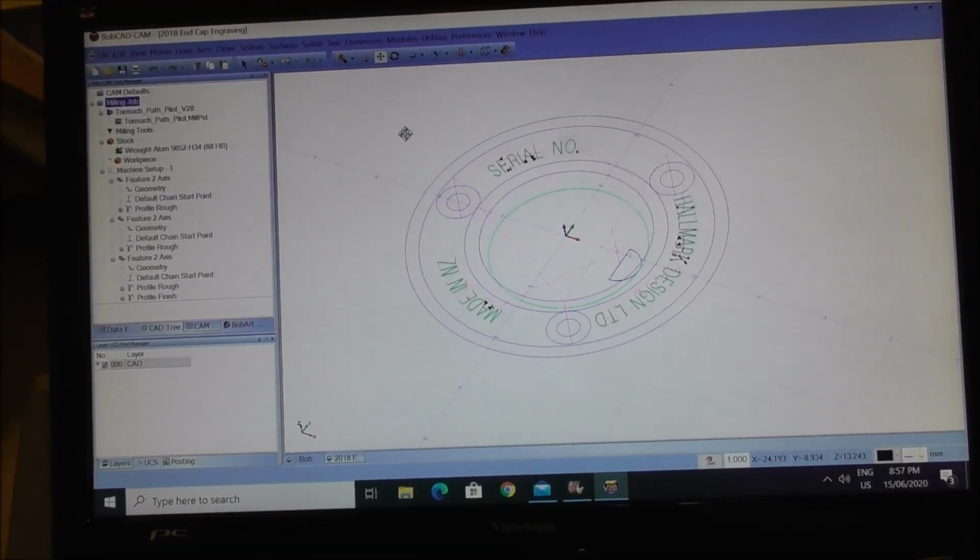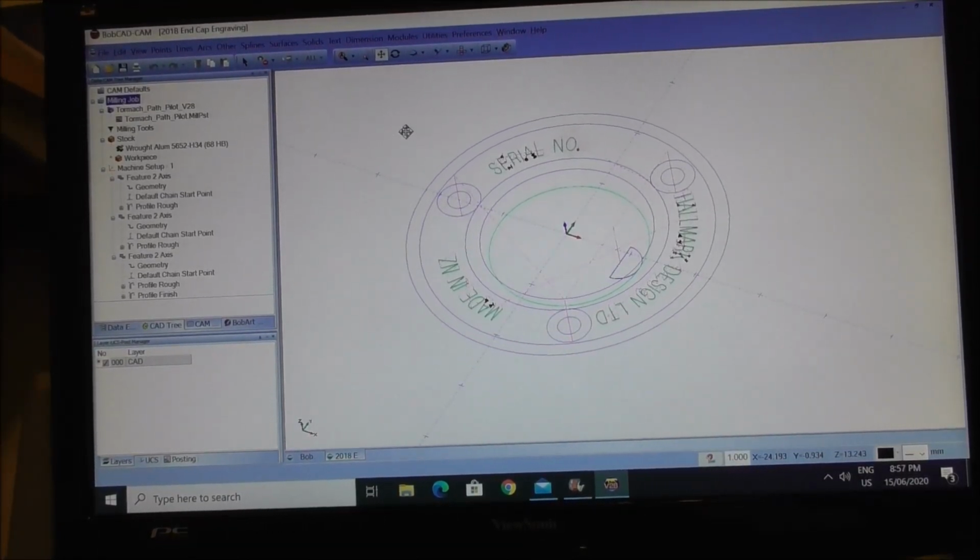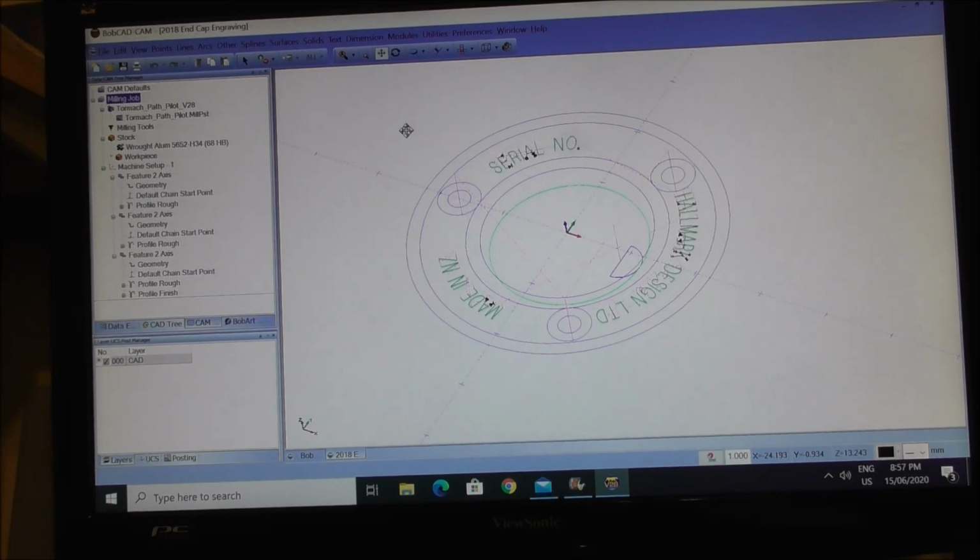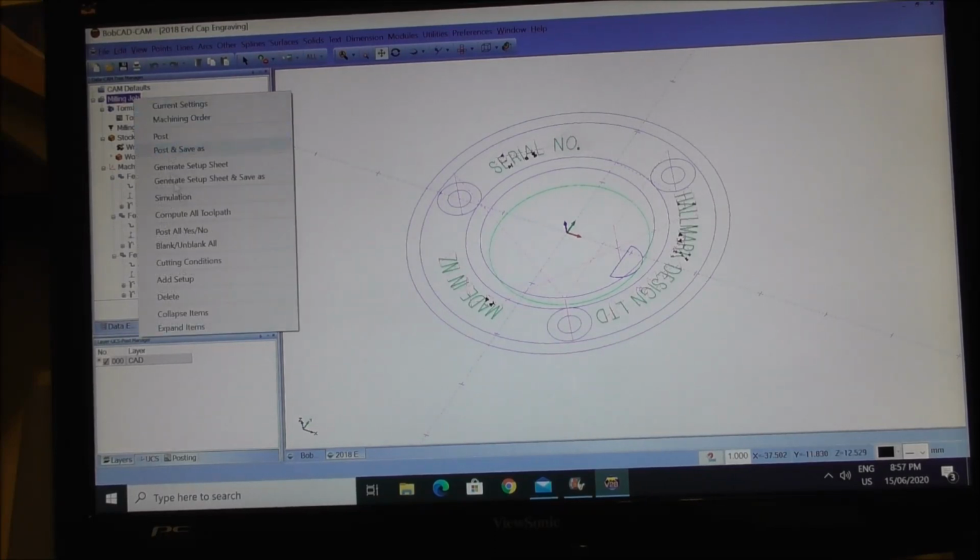There's different ways of producing the G-code with the multiple offsets. You can probably go back to your CAM software, in Fusion 360, or here I'm in Bobcat CAM, and depending on how your post-processor is set up, you can probably generate the code that's got the different work offsets so that you can go straight in and just use that code directly. But there's a couple of disadvantages with that.